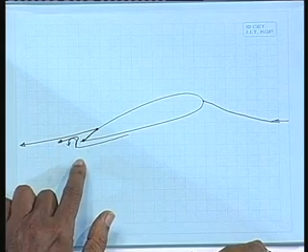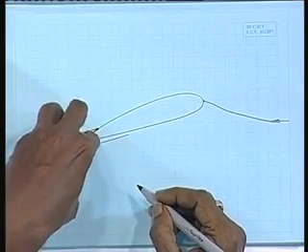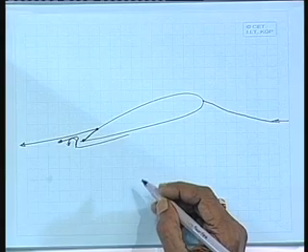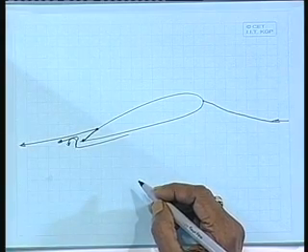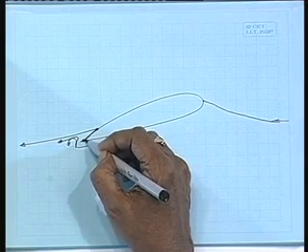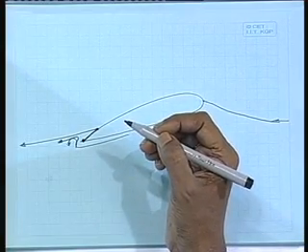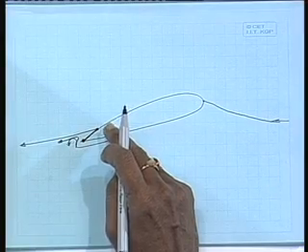Can you see that? And this is unsteady. So, this vortex that is being shed is going away from the trailing edge, it will pass, and slowly the unsteady flow will become steady and the stagnation point will move. So, this vortex that is shed is called the starting vortex. It is not continuously being shed, it is shed only at the starting of flow because of the initial pressure distribution causing unsteady flow. So, this vortex is shed and gone.